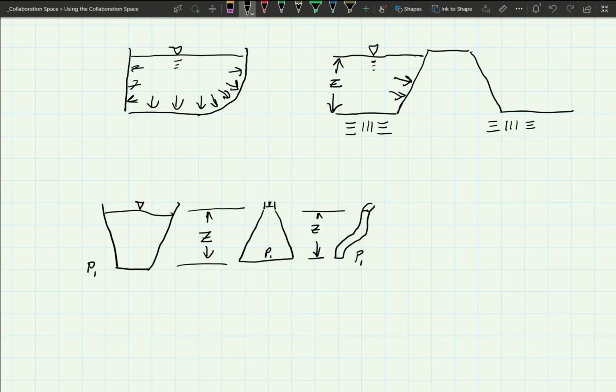So literally, if I have a reservoir that's 400 feet in the air, and I go to another reservoir, the pressure at the bottom of this higher one could be the same as what's down below at its equal depth. Okay? One thing is going to change: we've got the earth involved. But ideally, as long as the depths are the same, it's the same pressure.